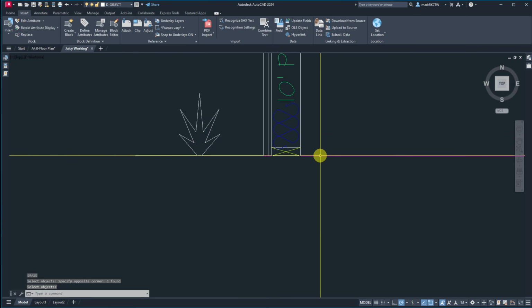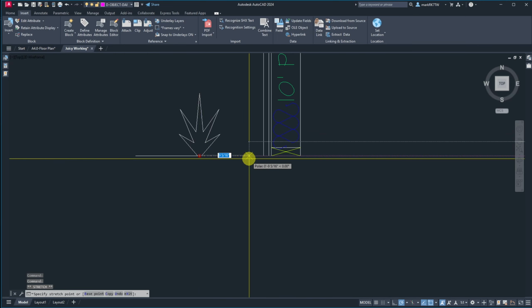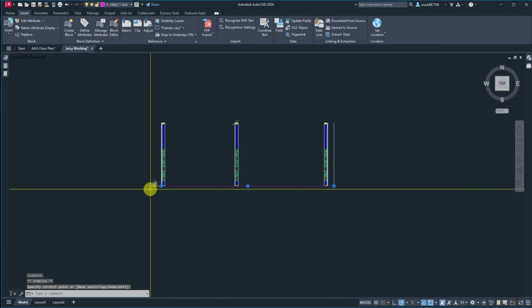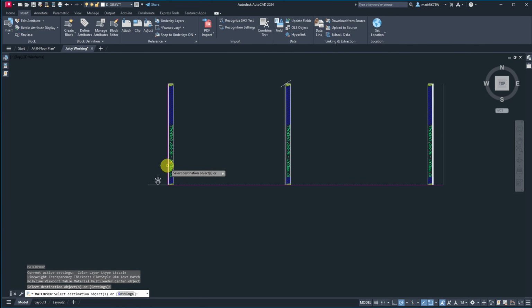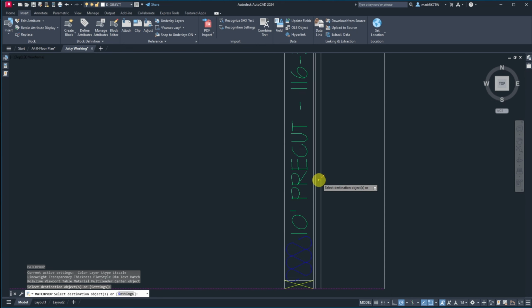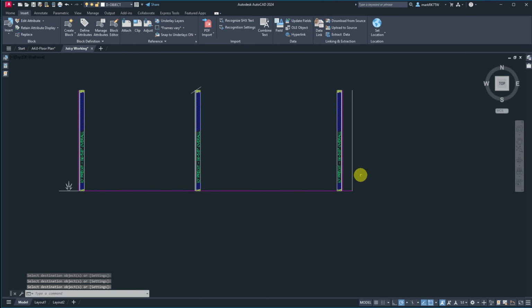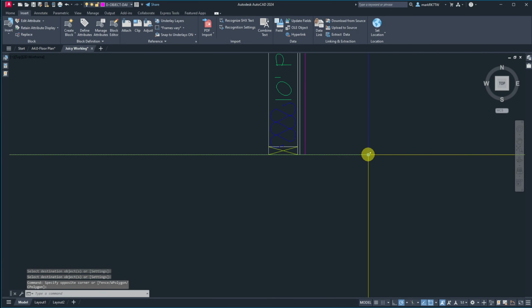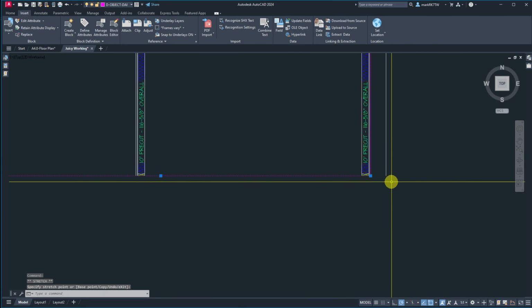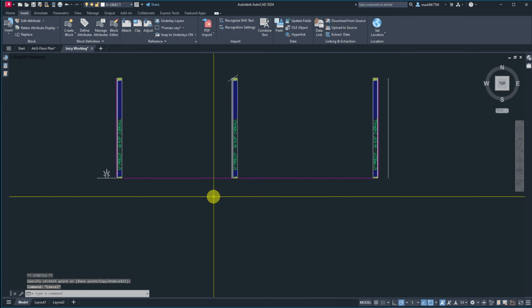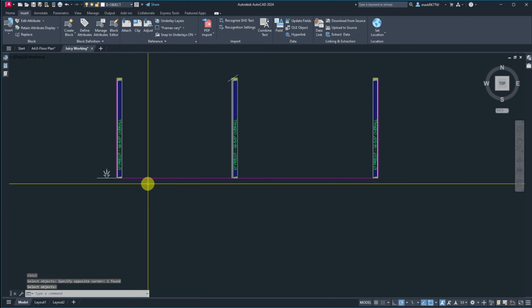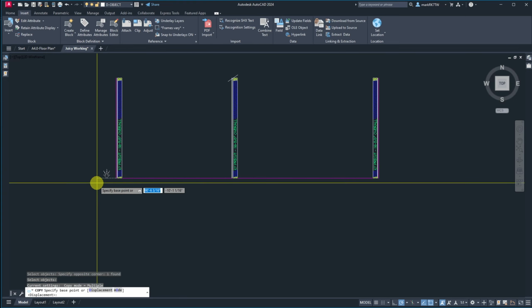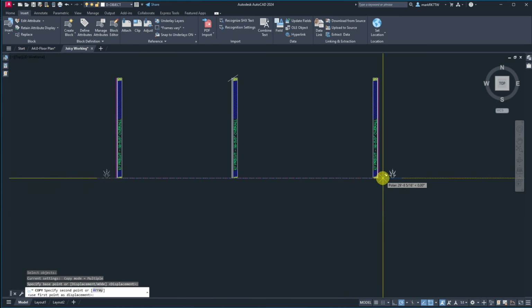And then take this and drag it back because that magenta is a much darker line. And then I want to turn this to outline, to have a dark border outline on my elevation. So I can now get rid of that. It was just there to trim, and we can make a copy of this and put one at this end as well.